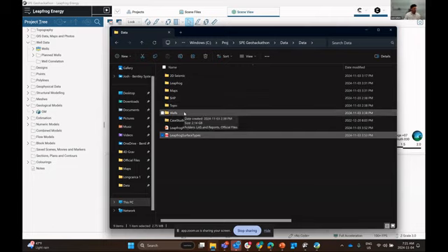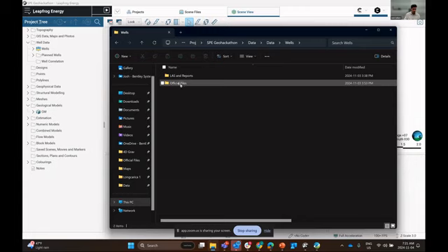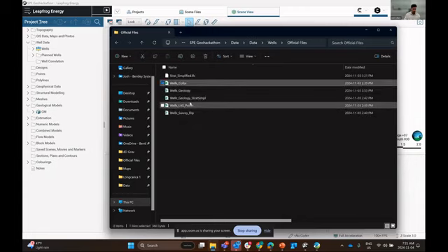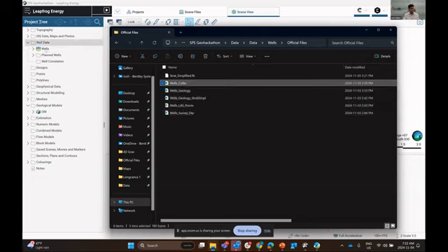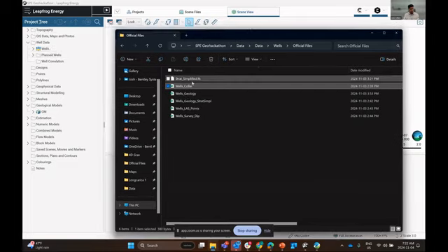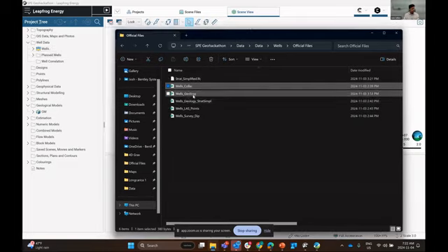So one of the most important objects that you can visualize within Leapfrog is your drilling information. If we look at the wells folder and the official files, we have these 5 different files that we can use to construct and create 3D well log interpretations. To create these 3D drill hole objects within Leapfrog, we do need it in a specific format. Generally speaking, you will need a collar, a survey, and some sort of downhole interval or point information.